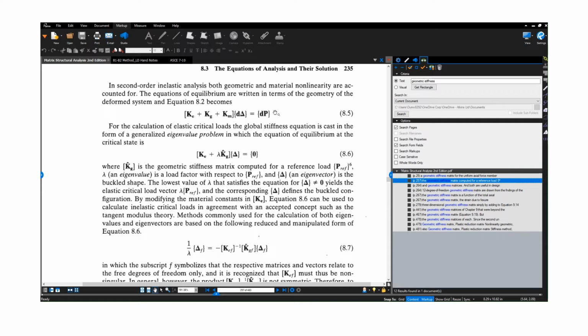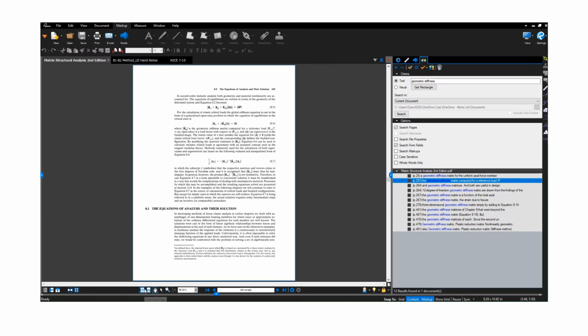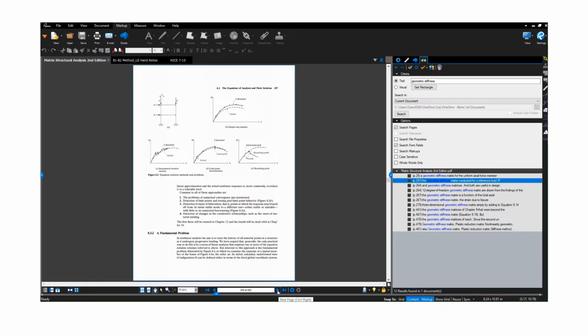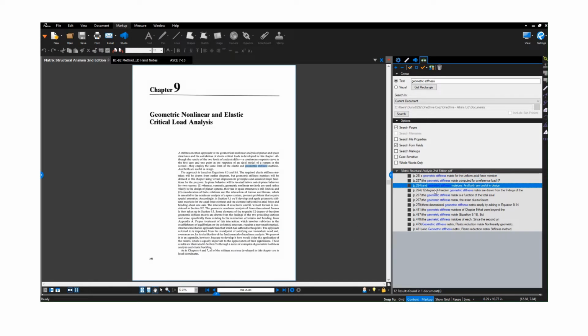But either way, you end up with the force matrix, and the axial load has a destabilizing or reducing effect on K sub E, and that's taken into account, like I said, by the direction of the sign of the axial load, and compression will cause it to reduce.